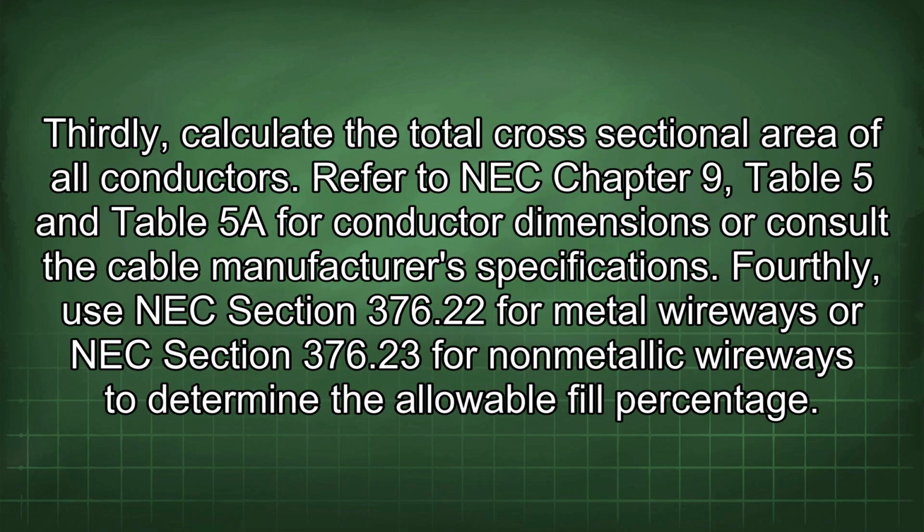Thirdly, calculate the total cross-sectional area of all conductors. Refer to NEC Chapter 9, Table 5 and Table 5A for conductor dimensions or consult the cable manufacturer's specifications.